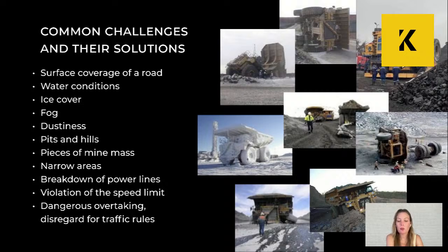Fog is another issue. Many quarries stop working during foggy conditions, but there are solutions like installing specialized fog lights on power poles to guide vehicles. Ultimately, how to handle fog is up to the technological personnel managing the quarry. Dust can obstruct visibility and harm the respiratory health of employees. Combating dust is straightforward. Just irrigate the top layer of the roads and use reagent that absorbs small rock particles, keeping them on the road surface.